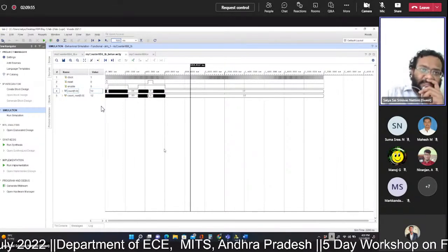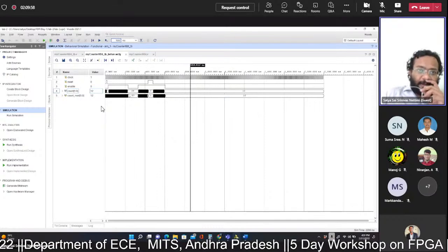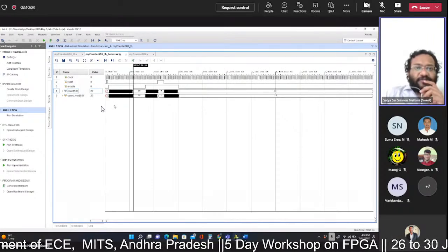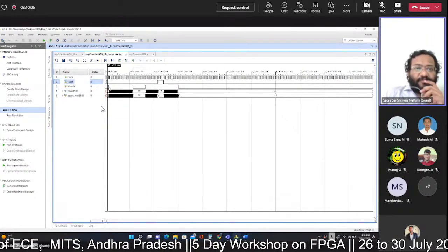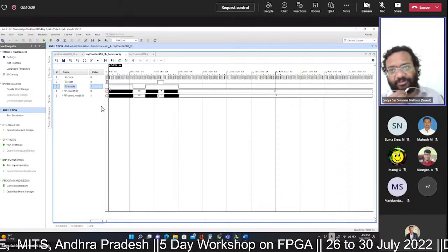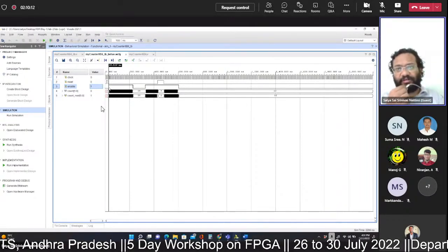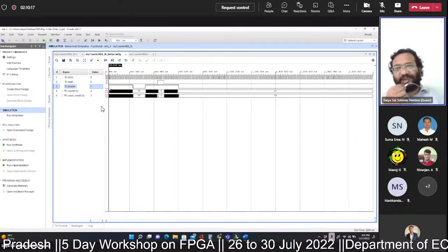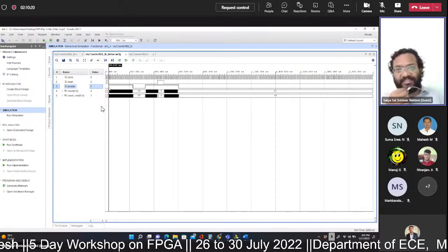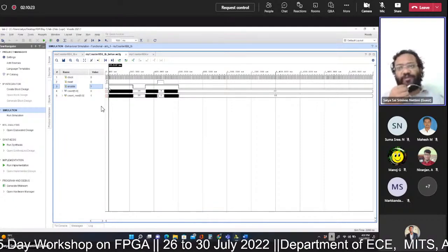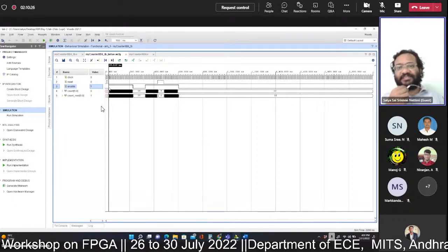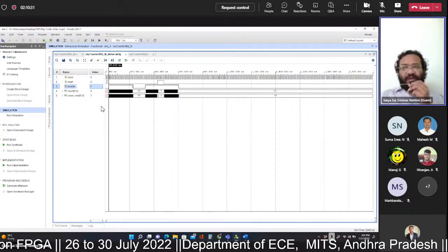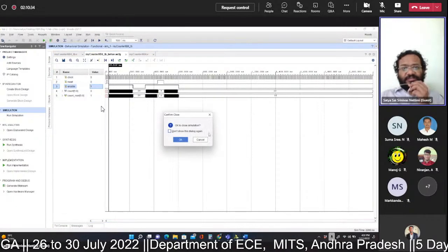So all our test cases we have verified in our test bench, and the module is working as per the desired functionality. What we can conclude from here is that the HDL description we have written is meeting the desired functionality. But we don't know whether this description is a valid description or not, whether we can get a valid circuit out of this or not. How will we know? We will know once it is perfectly synthesized and implemented. In this way, generally we write test benches to verify our digital circuits.